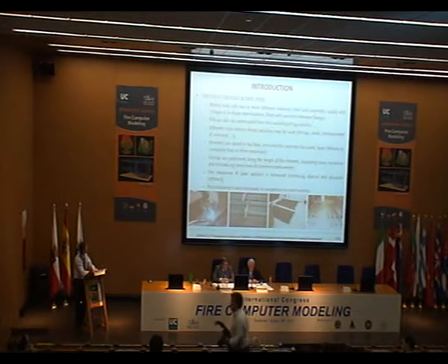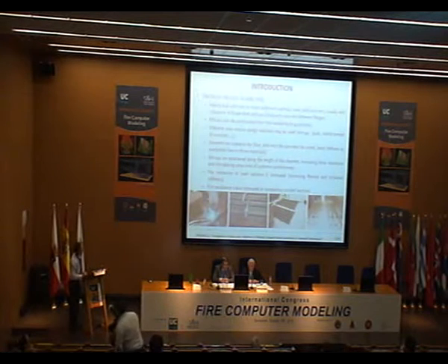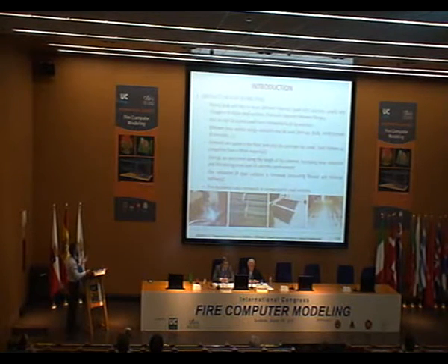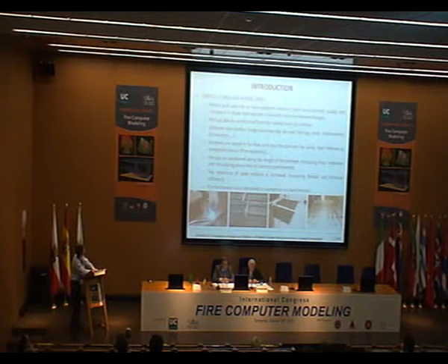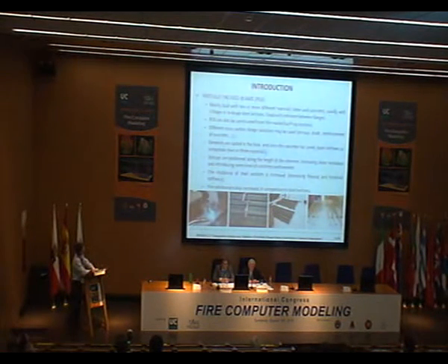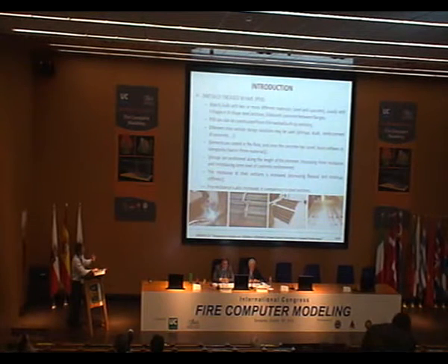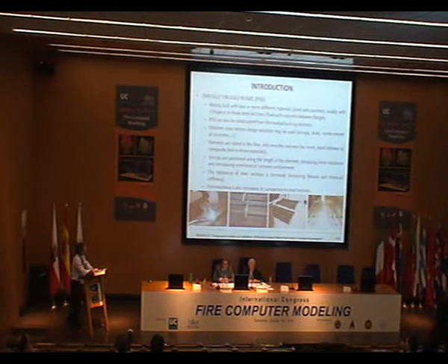the conclusion. So, partially encased beams are mainly built with two or more different materials, normally steel and concrete. Usually they are built with I-shaped or H-shaped steel sections filled with concrete between the flanges. They can also be constructed from thin-walled built-up sections. We can manage different cross-sections, and different design solutions may be used, so we can change the stirrups, the studs, the reinforcement of concrete, and so on.